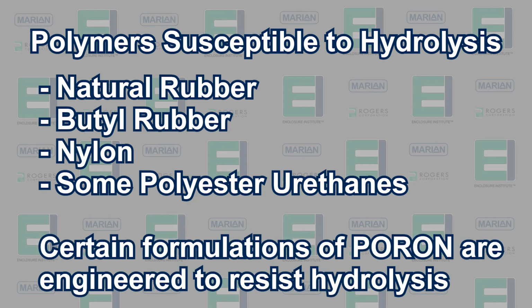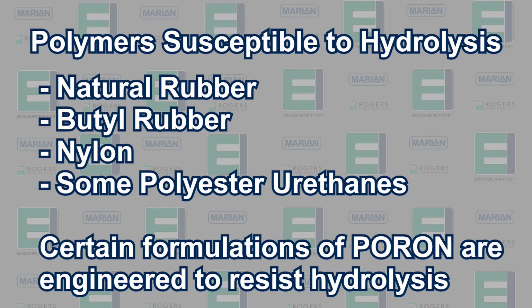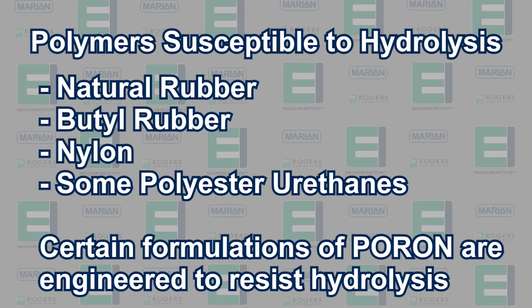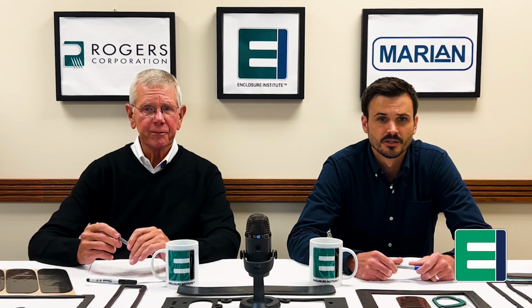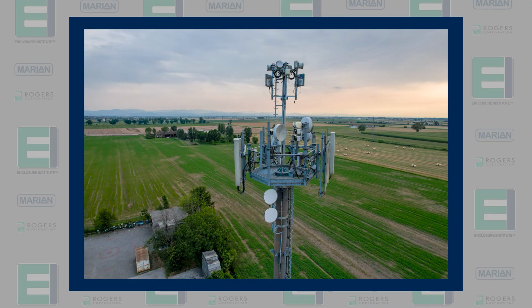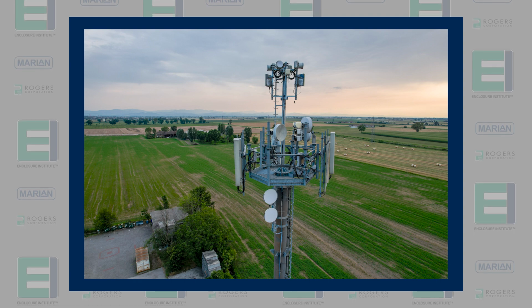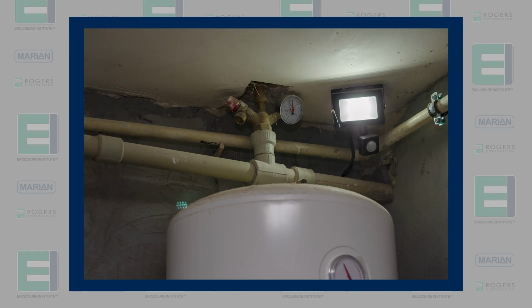However, certain formulations of pour-on urethane foams are engineered to be highly resistant to hydrolysis, making them well suited for environments where moisture exposure is common. There are many applications for devices installed in very humid or moisture cycling environments. An example is telecom equipment mounted high on towers that are subject to rain or ocean salt spray, or meters and controllers installed in wet basements or underground tunnels.